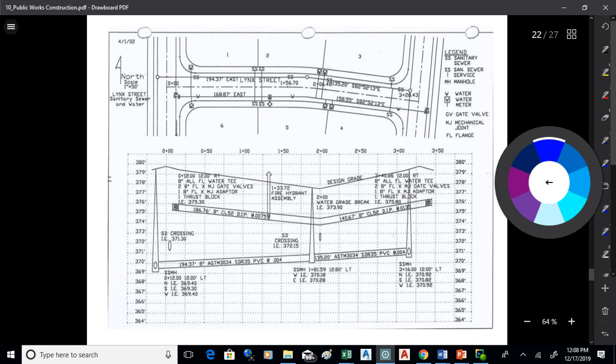So what we have going on here is we have a T intersection. Those bow tie symbols are valves. The little triangle is called a thrust block, which helps absorb kind of water hammer when we create a T like that. And then we have labeled the line with a W. Okay, we've got the distance and bearing on the water line as it works its way across.